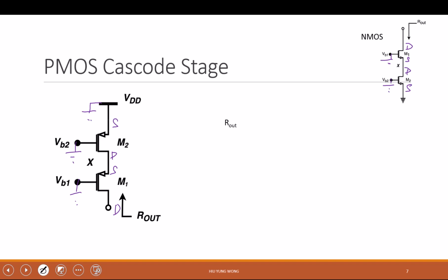So naturally, I will know that this output impedance must be the same as what I learned earlier. Based on this circuit, I know that this output impedance, if you forgot, is equal to RO1 times (1 plus GM1 RO2) plus RO2.